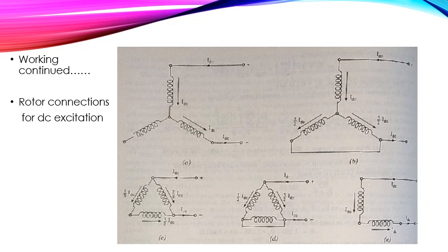Now, as can be seen from these diagrams, the current distribution in this figure is unbalanced, and unbalanced secondary heating is unavoidable with a three-phase secondary. But the two-phase arrangement, as shown in figure E, equalizes the heating. Right? Now see figure E. Here the unbalanced heating is there. Why? Because only two windings are used.